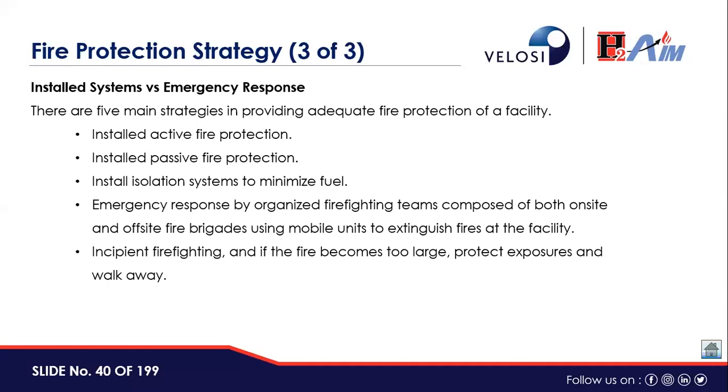And the firefighting system also has two parts. One is passive fire protection, the other is active fire protection. Passive means fireproofing and those kinds of things which prevent the collapse of the structure on an immediate basis. Whereas firefighting systems mean the water-based system, foam-based system, clean agent-based system, or portable extinguishers as well. Then there is the installed isolation system, basically the ESD system, which in case of any emergency can isolate incoming fluids and release the fluid by the relief system or through the flare system.